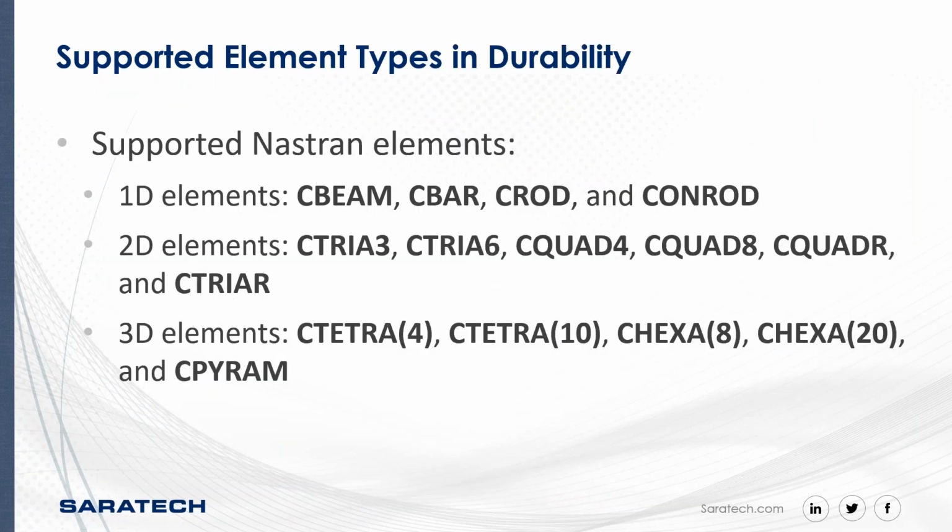Okay, so the supported elements in durability are your basic elements: your 1Ds, which are your beams, bars, rods. In 2D, you have your trias, your quads, and in 3D, you have your tets, your hexes, and your pyramid elements.